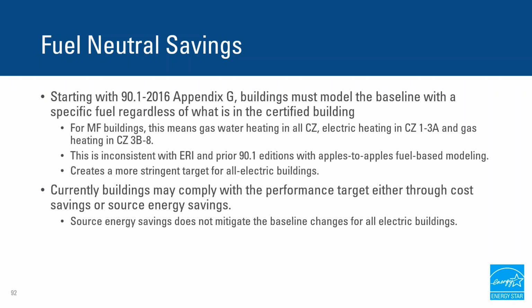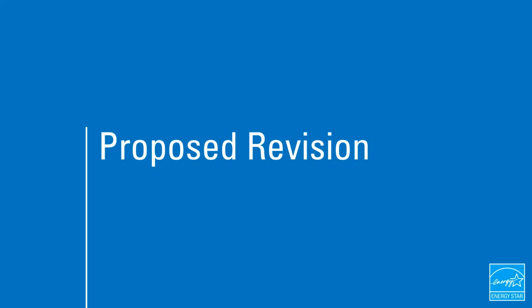And having this is inconsistent with how it's modeled in the ERI and previous 90.1 editions, which would have apples to apples fuel-based modeling. Ultimately, this creates a more stringent target for the all-electric buildings. And so it's a challenge given the cost of electricity compared to the cost of gas. We, for our program, allow folks to use either the cost savings or the source energy savings, but even source energy savings does not fully mitigate the challenge from this baseline change.